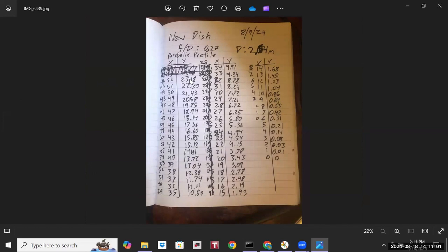And so I can take that value, where 52 inches is the outer edge of the dish, and it's supposed to be just a little over 23 inches above the vertex vertically. Then I can measure that from the floor, accounting for the feet and the base and the thickness of the rib itself, and figure out how high it's supposed to be. When it's all the way open, it should match that value. And now I've got it a lot closer to where it's supposed to be. I guess, does that answer your question?